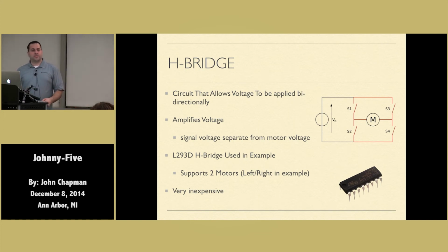We talked about transistors earlier, which basically says I can use a 5-volt signal to control a higher power motor. In this particular case, I'm using an 11.1 volt battery pack, and I'm driving those motors with over 11 volts. These particular motors are 9-volt motors, but they haven't blown up using 11 volts, so more power.